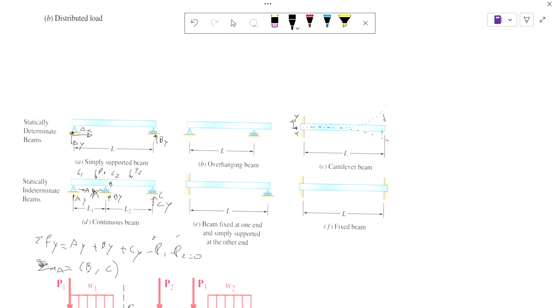But you use these cases when, say, you start from here and the forces are too large. Then, knowing that force, determining By, you can say, oh, okay, we can break By in two, and then say By half here and By half here. And then in that case, you can design that beam like that. But you have to start somewhere else. And from a design purpose, you can just add Cy to your design. So I'm not going to put that into your notes so they are not confused.